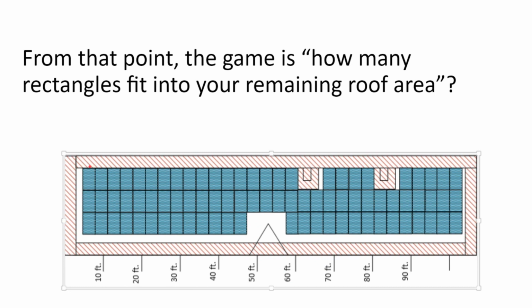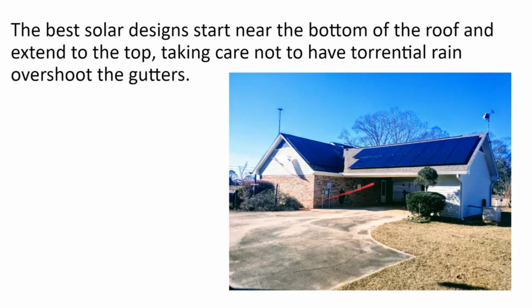Of course, the taller and skinnier the building is, the harder it will be to take that building completely off grid. So at this point, a design algorithm emerges for selecting the ideal roof surface for planting a solar array on the roof. Start by identifying large, open, sunny areas on the rooftop. South-facing surfaces are best, but anywhere between due east and due west is just fine. If the roof has a 5/12 pitch or less, consider the north side of the roof as well. In other words, if the rooftop is walkable, the north side of the rooftop should still be considered as a potential site.